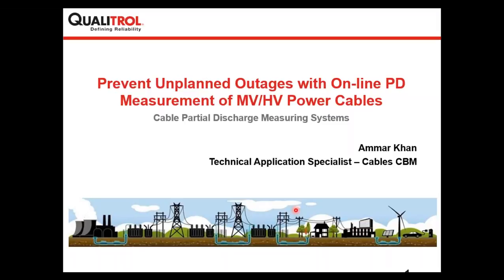But there is another argument. If you read the literature, different research papers, there is an argument that when these water trees are dried out, they can lead to partial discharges. But one thing we need to note here is that when water trees are dried out and start giving partial discharges, they will be transformed into electrical trees very rapidly. And as soon as you have electrical trees in the cable insulation, it will lead to failure or breakdown of the cable insulation very rapidly.